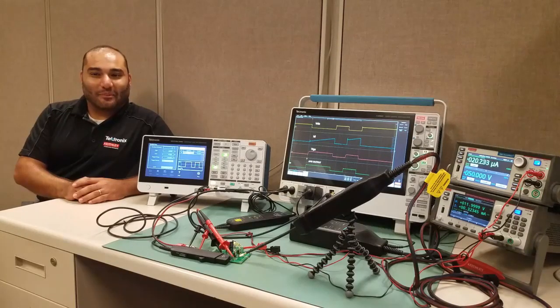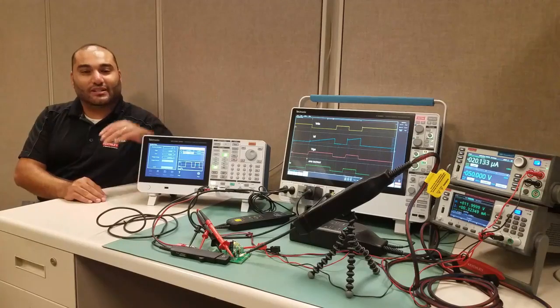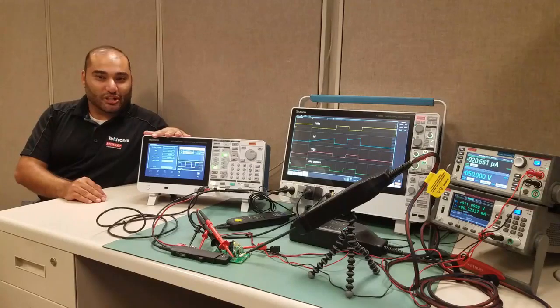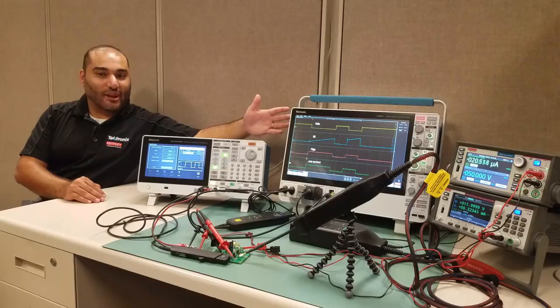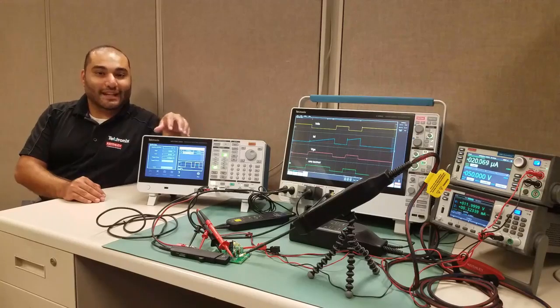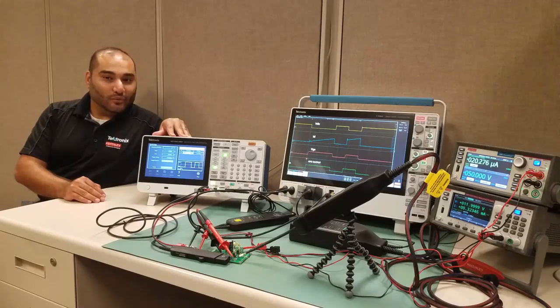Today, I'll explain what the double pulse test is and why engineers perform it. I'll show you how to use the double pulse application on a Tektronix arbitrary function generator, AFG31000, to set up your pulses in less than a minute. We will also show measurements on a Tektronix oscilloscope, MSO5, to measure our parameters. We will be doing this test using an ST micro eval board, a Keithley SMU, and a Tektronix IsoView probe, a current probe, and a differential probe.